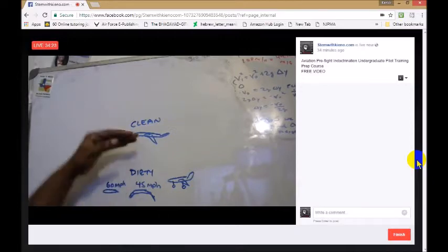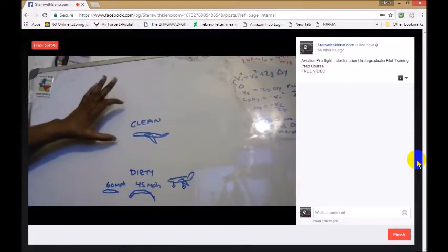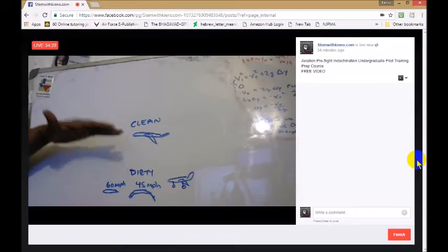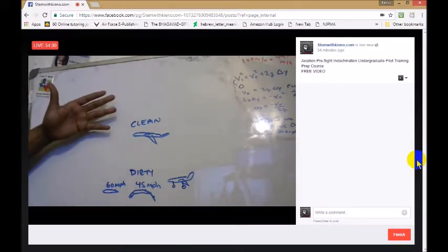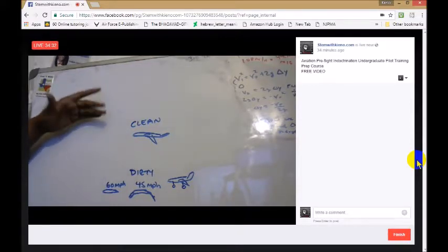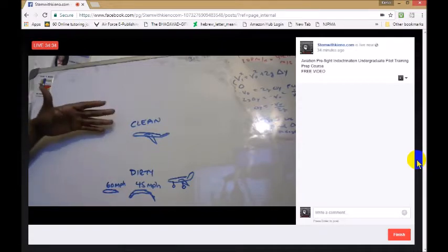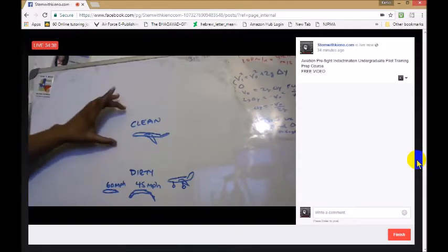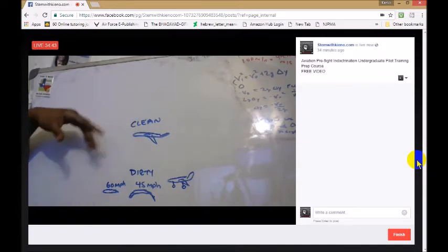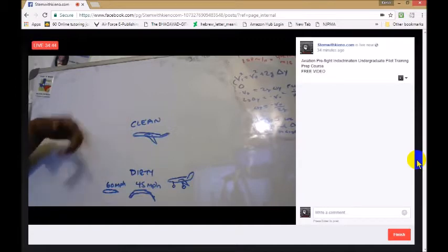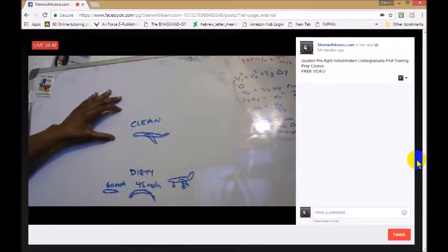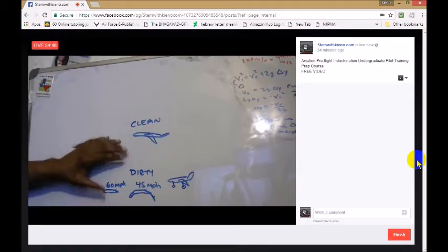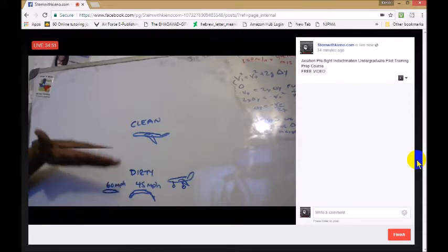In the clean configuration, we don't have a lot of things protruding, causing interference drag, or form drag, as we would call it when we're discussing drag. Basically, in the clean configuration, the flaps are up, and the gear is up, and this is the configuration that we will be in on a climb out. Whereas in this configuration, we want to be as slow as possible.